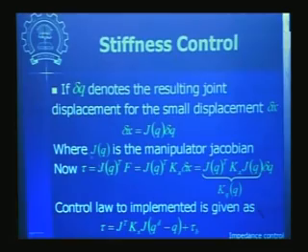Okay. Now see, why we are doing all this computation is basically we want to know how much torque we should apply at our joints, or what is the scheme to apply the torque at the joints, so as to produce this type of force or this type of stiffness characteristics for the end effector when it starts interacting with the environment. Okay. After that we convert this delta x by using the Jacobian to delta q in this fashion.